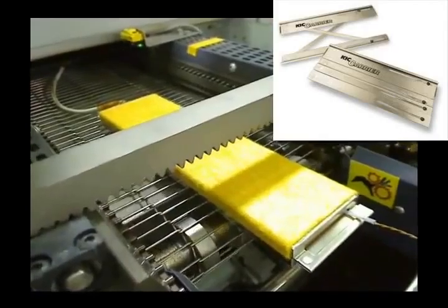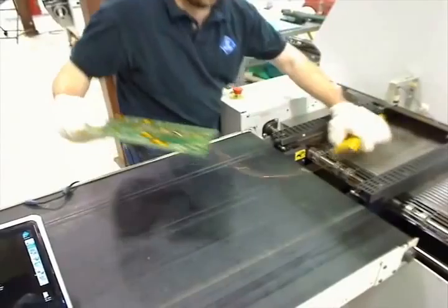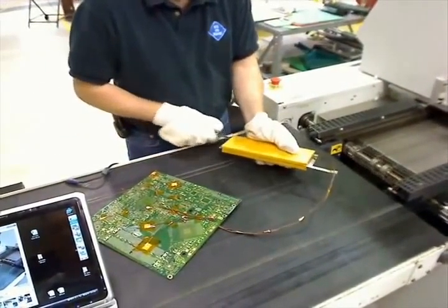In this example, the profiler is loaded into the oven by hand directly onto the belt conveyor. If your oven does not have a belt, a common method is to use a scrap board or an adjustable carrier. If you are using an RF profiler, data will begin to populate your profile graph immediately.